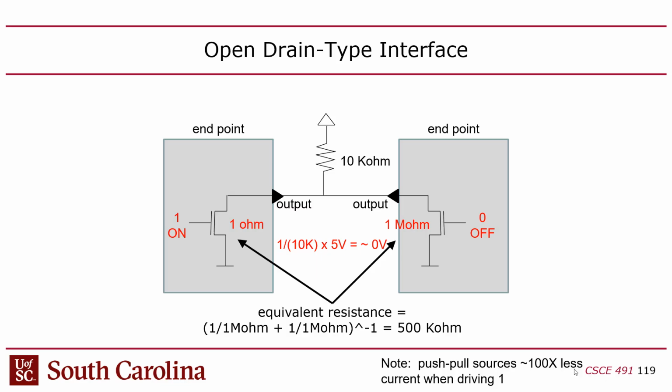Right now I'm just talking about open drain, but I2C uses open drain. So I'm talking generally about open drain at the moment, but I'll get into I2C in just a second. Anyway, that's the principle: if no one drives it, if no one pulls it down, then the default state of that signal is logic 1, it's going to be high.